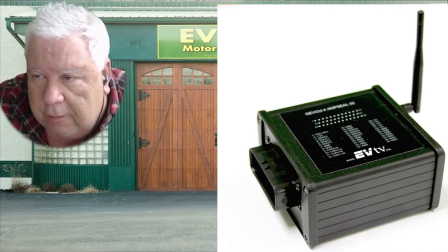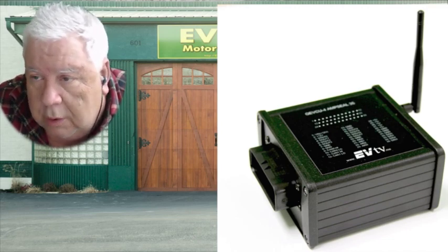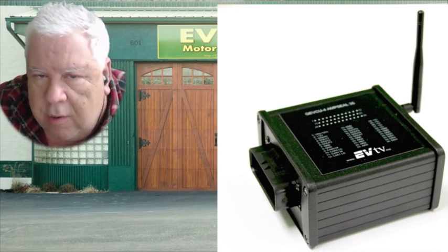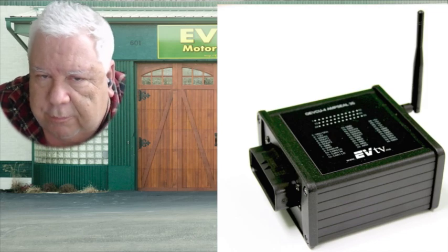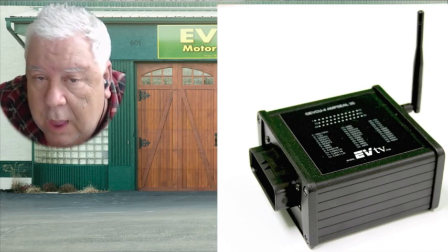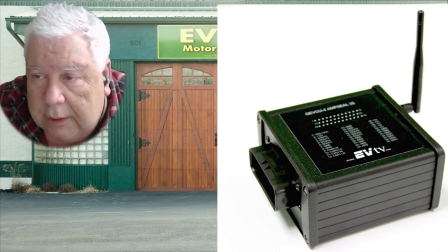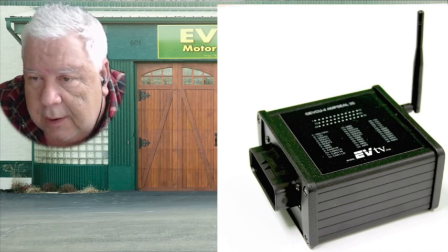And so we have taken that and done our own board with one USB port and brought it out to this Amp Seal 35 connector and hardened it and put some DC to DC converters in it, cleaned up the power supply thing where it's suitable to work in an automotive environment. With a more limited set of inputs, we can do 4 analog inputs and 4 digital inputs and 8 digital or analog outputs. And so it's sort of a limited set of Arduino.